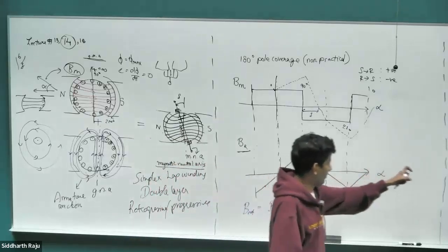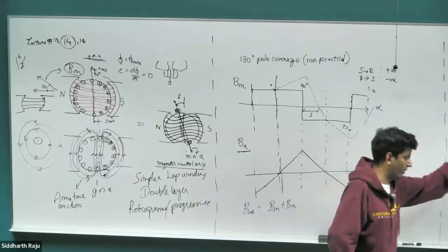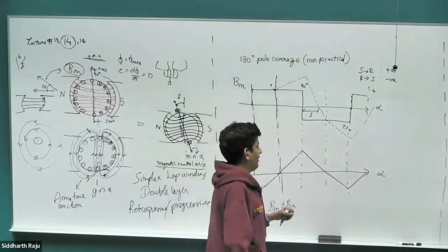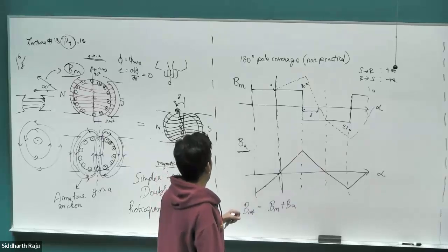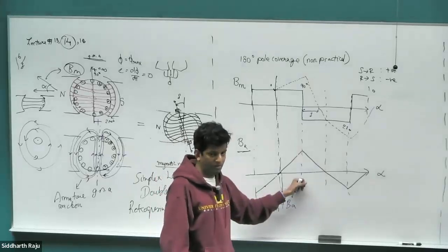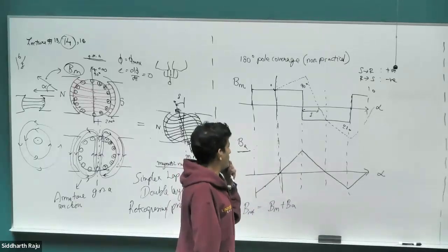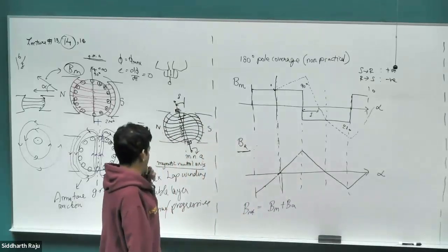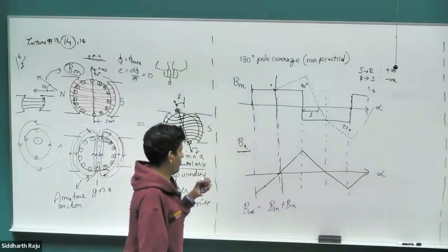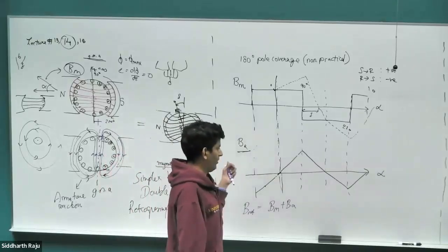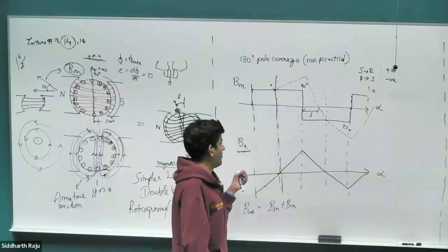Yeah, so we are going to assume that the core of the magnet as well has infinite permeability, which is not a real assumption either, but we are going to go ahead with it for now. Right? Everybody clear on this part? The summation? Okay. So there are a couple of solutions. The one solution we can do is, of course, shift the magnetic axis, but that then has its own problem where it is only applicable for a particular current and a particular direction of current as well.